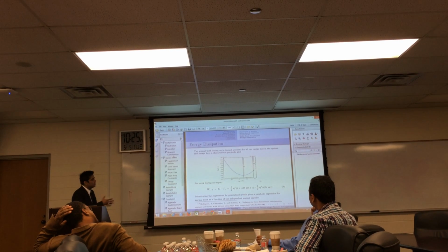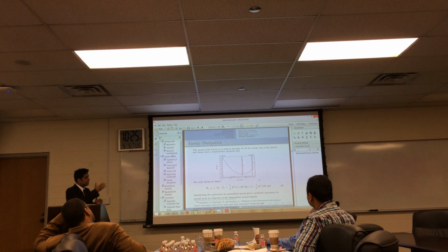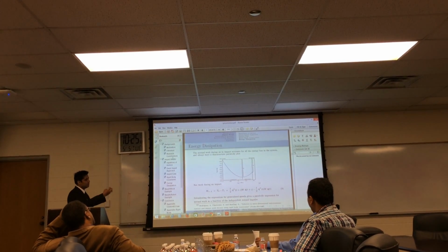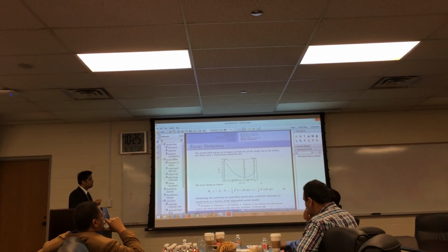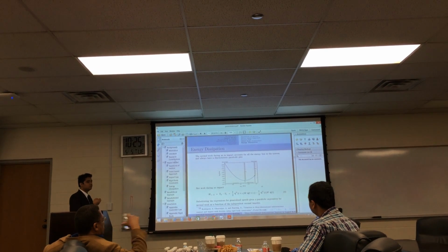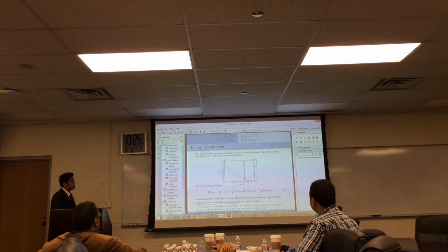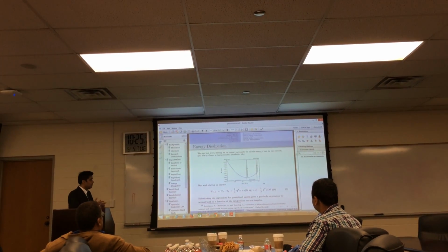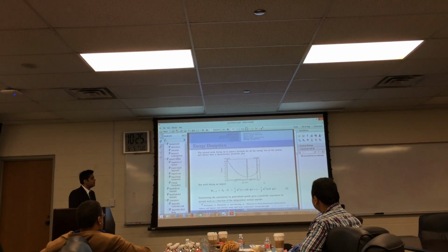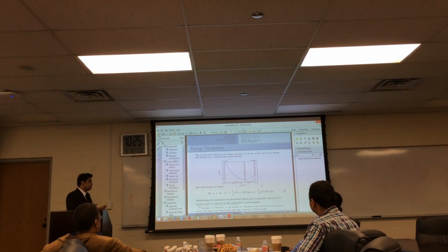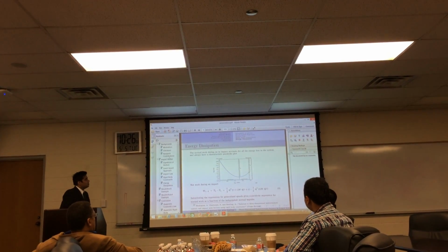So next, basically, as I explained in the previous slide, we can reduce all the velocity in terms of one independent impulse, the normal impulse. So next we will have to find how to compute that normal impulse over the impact event, and that could be done using the energy dissipation, sort of setting how much energy we want the system to lose during the impact.